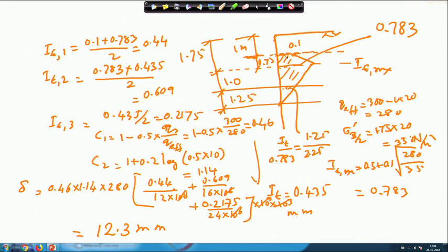So, base of the footing is this and b by 2 is 0.75. So, this depth becomes 0.75. So, that means the total depth from the surface, I max becomes at 1.75 meter depth, and this is the depth of the first layer also. That means, the depth of the first layer and the I max are coinciding. So, beyond that I will not consider, but from here I will be considering.